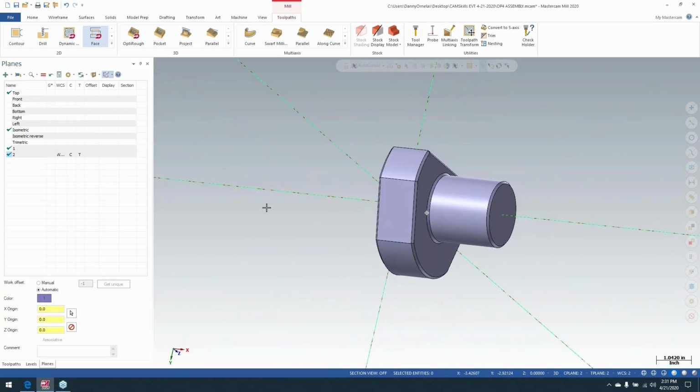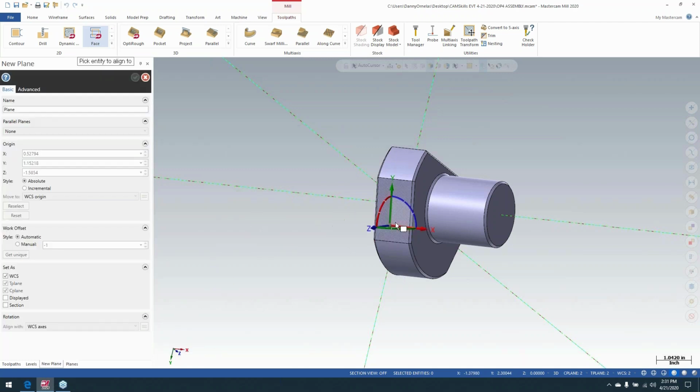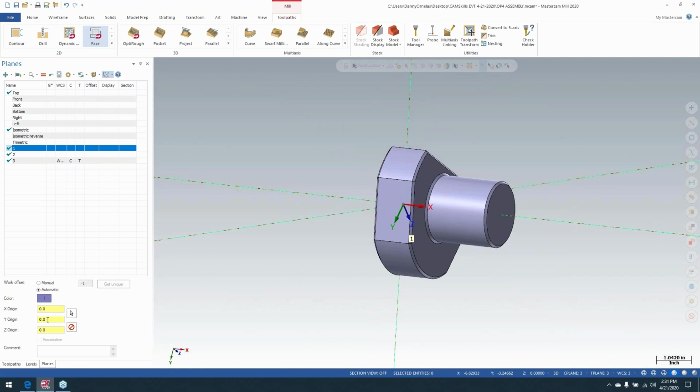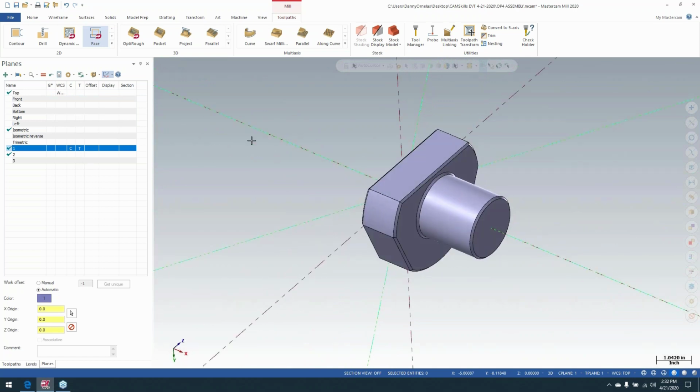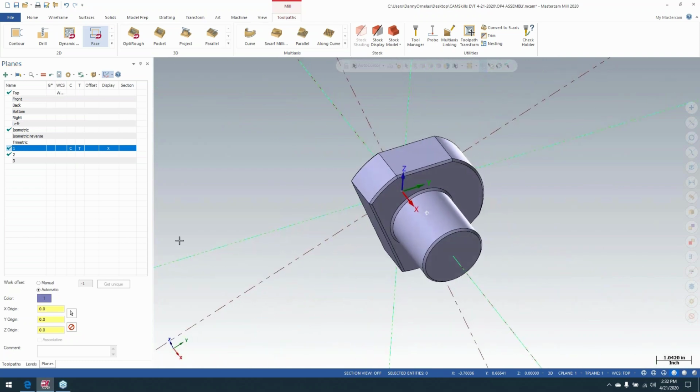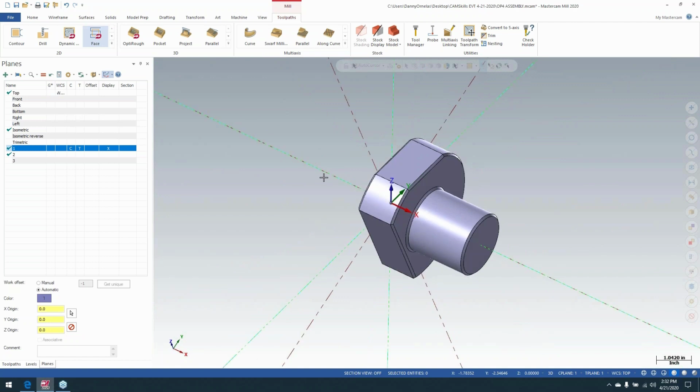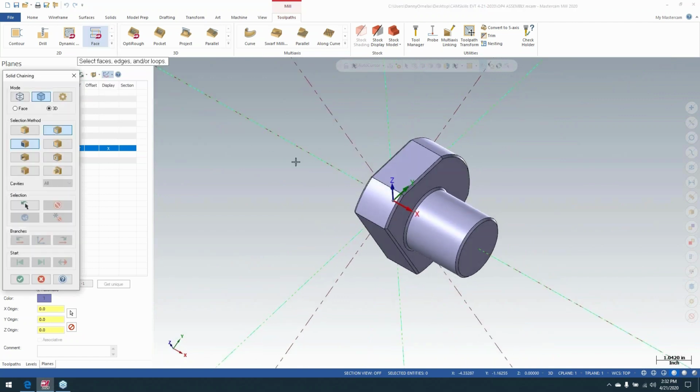Spin this part around graphically here. And then I'm going to do this face. Pick this face right here, call him 3, and move him to the origin as well. So all of these are at 0, 0, 0. They're not anywhere else. They're just different views. So if I go to 1 here, let's put it all in the top plane. I want to set up my construction plane here for 1, which is this one, I believe, right? Display. Oh, it's this one right here. Sorry about that. I'm going to put a toolpath on there. So I'm going to say facing.